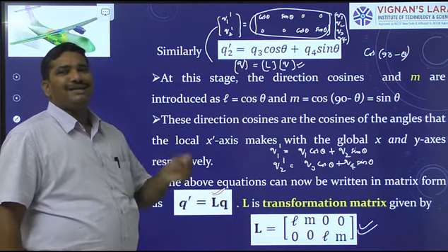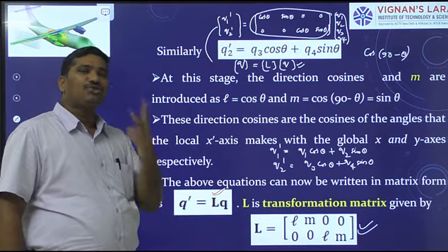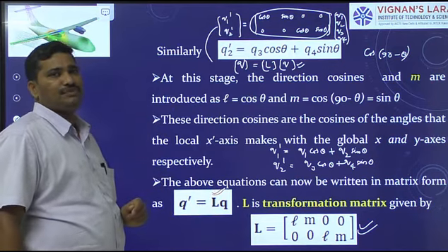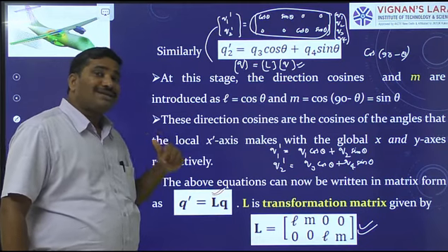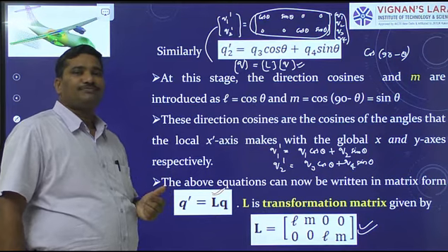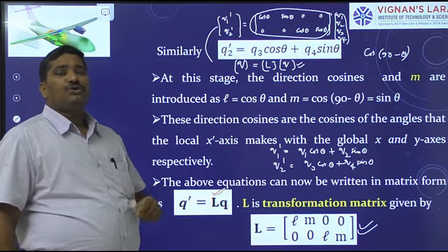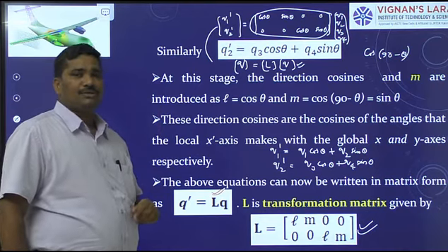Each node in the plane of the truss has 2 degrees of freedom, and each truss element with respect to its own reference frame has 2 degrees of freedom, with 1 at each node.